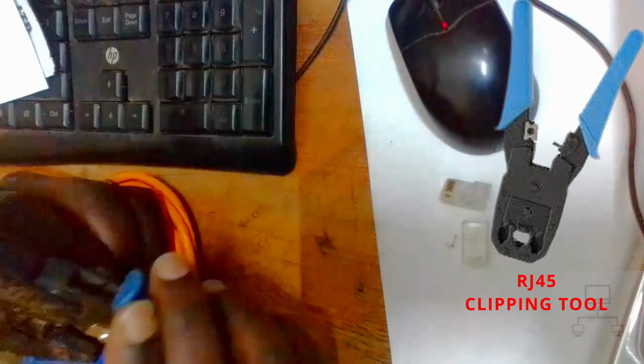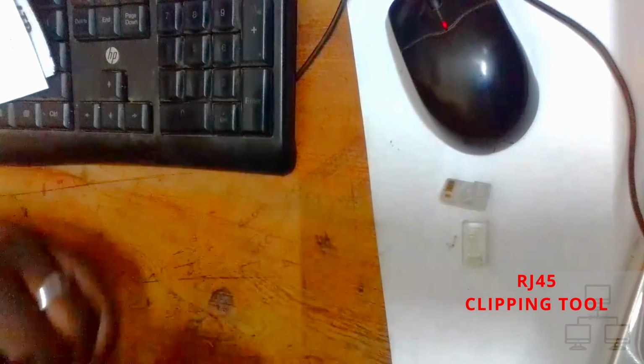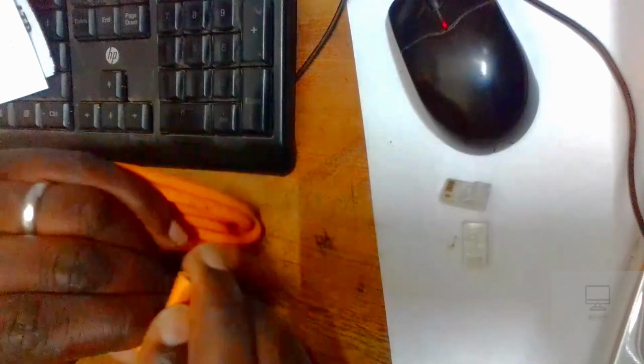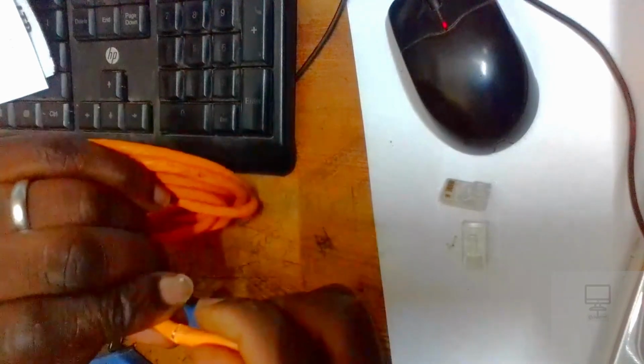With the help of a clipping tool, we are going to put our RJ 45s on both ends of the Cat 6 cable, and we shall start with cutting off the insulation or the outer skin of the cable.